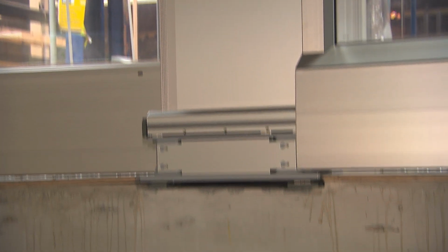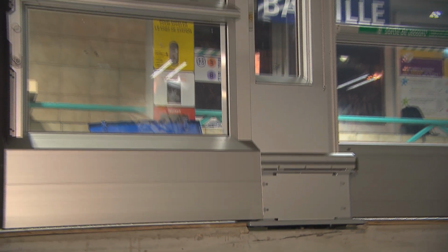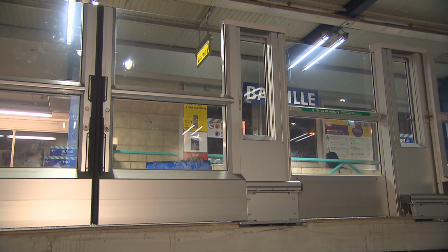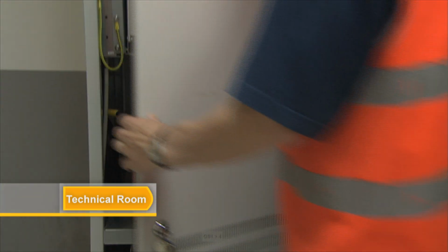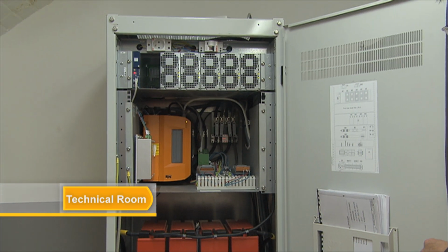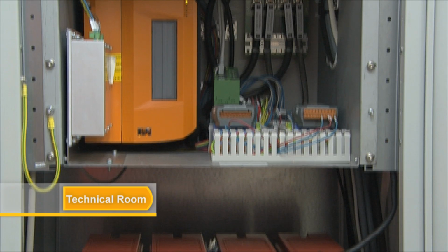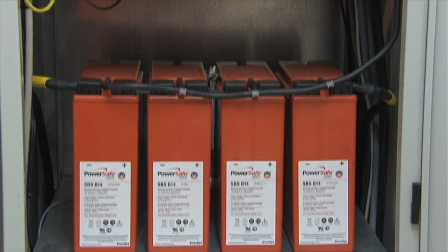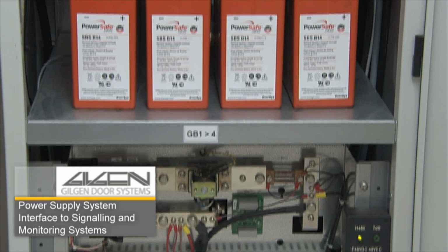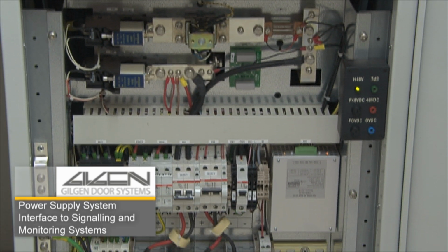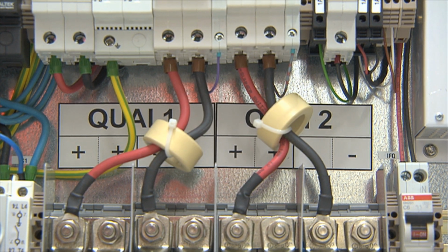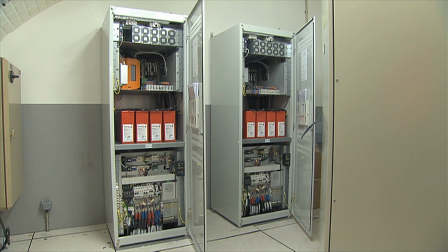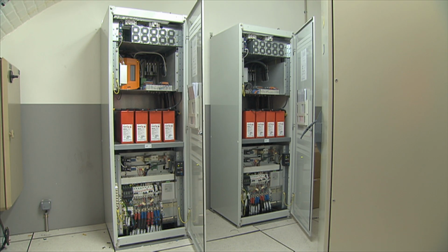To a certain extent, existing cable ducts can be used for the cabling between the elements in the technical room and the ones installed on the platform. Among others, the PPS and PSC cabinet includes the PSD power supply, PPS, and the PSD station controller, PSC. These components ensure the following main functions: processing of the power supply for all the doors installed on the platform, PPS, processing and distribution of the safety relevant and monitoring signals, PSC.